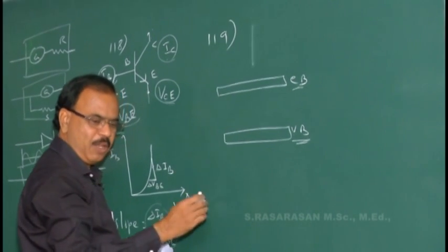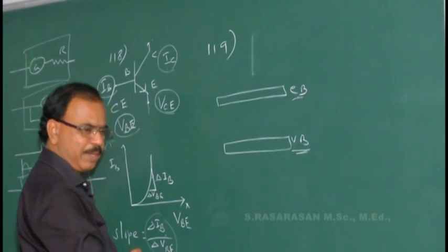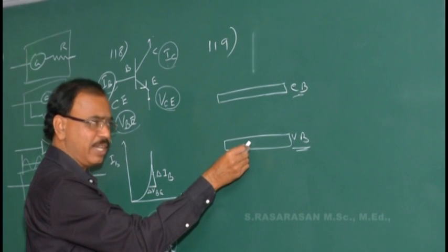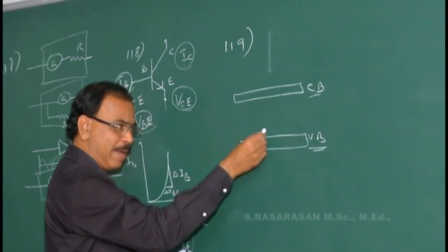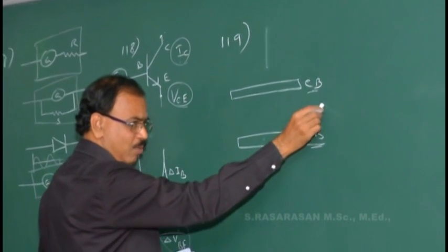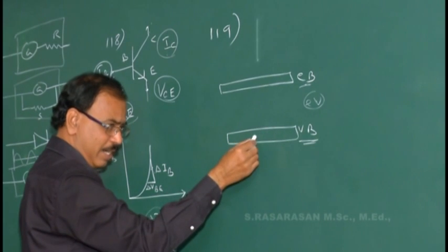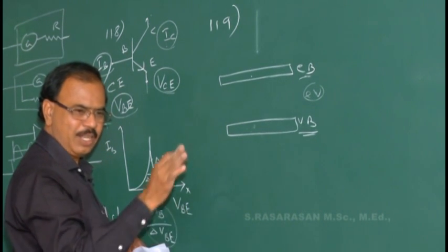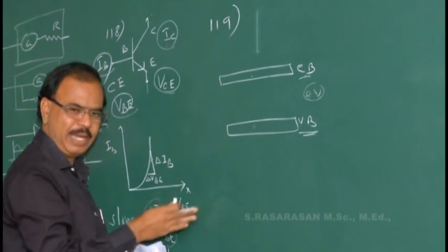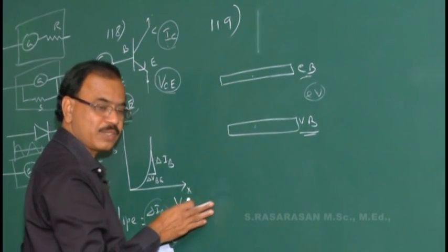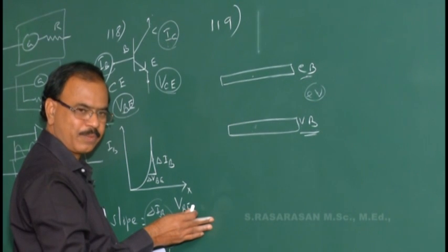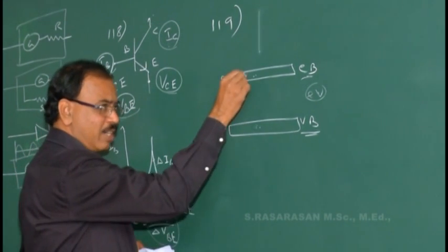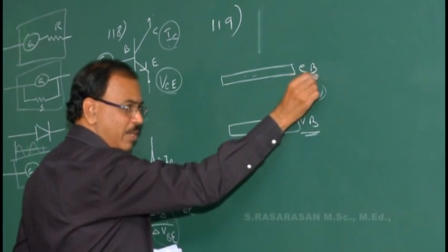What is conduction band? When we give some energy, potential or temperature, that energy is received by the electron in the valency band, thereby crossing over this gap called forbidden gap. This forbidden gap is measured in electron volt. The electron gaining the energy, crossing over the gap and entering that band is what we call a conduction electron. Whenever the electron is transferred from valency band to the conduction band, conductivity arises and current flows through the material. Such electrons are called conduction electrons, contributing to the conduction band.